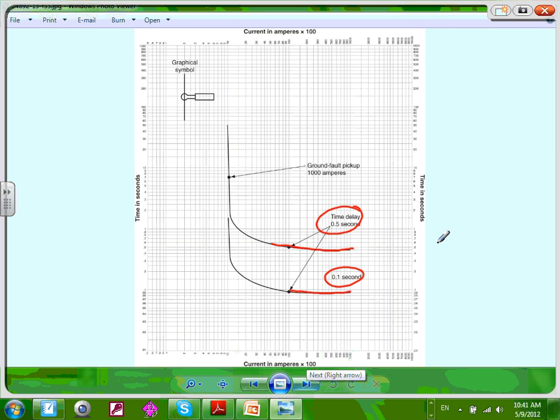You know who cares? If you have an arc inside your switchgear, it's a function of how long this short circuit or ground fault is going to sit in your switchgear. So that will decide the PPE, personal protective equipment or gear that you're supposed to put on yourself when you work on energized equipment. So that's a big deal for us.